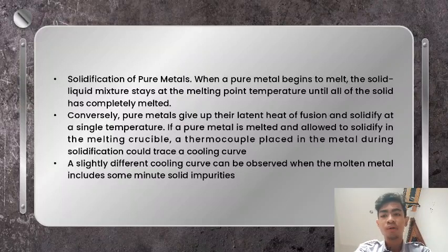It is also important to point out that undercooling or supercooling of liquids is a common phenomenon, while the superheating of solids is not. Liquid nuclei form much more readily when a metal melts than do solid nuclei when a solid cools. Liquid nuclei form first on the surface of the solid and spread out over the metal. Diffusion rates are also much higher in liquids, so melting typically occurs more rapidly than freezing.